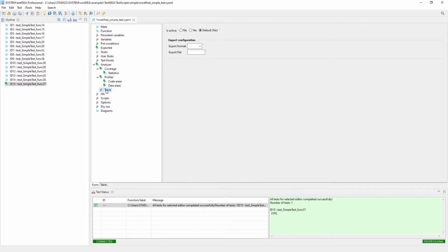The other features that are available here are the raw trace data. So this is just a recording of program or data trace. If you want to see a record of what the code actually did during the test, you could use that. Again, this does require the trace, or the slow run would actually work here since it's not recording any timing information. Only the profiler records the timing information.